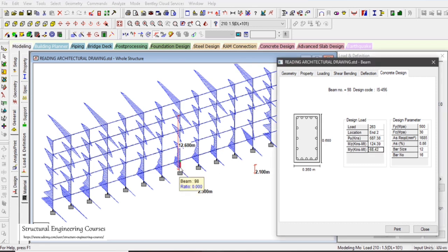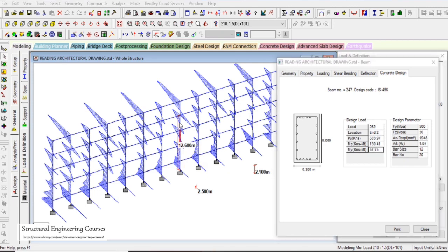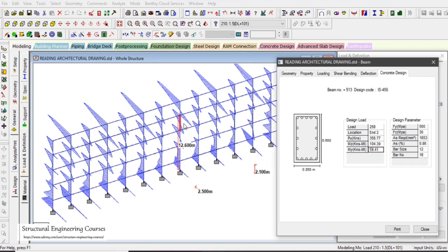So if we are providing this value 22.41, it is more than 16.85, it is lesser, and it is also lesser. So from this point to this point, we can provide the reinforcement to be 22.41 centimeters square, and for the top floor we can provide 28 centimeters square. So how exactly can you distribute this 28 value and 23 centimeters square value?